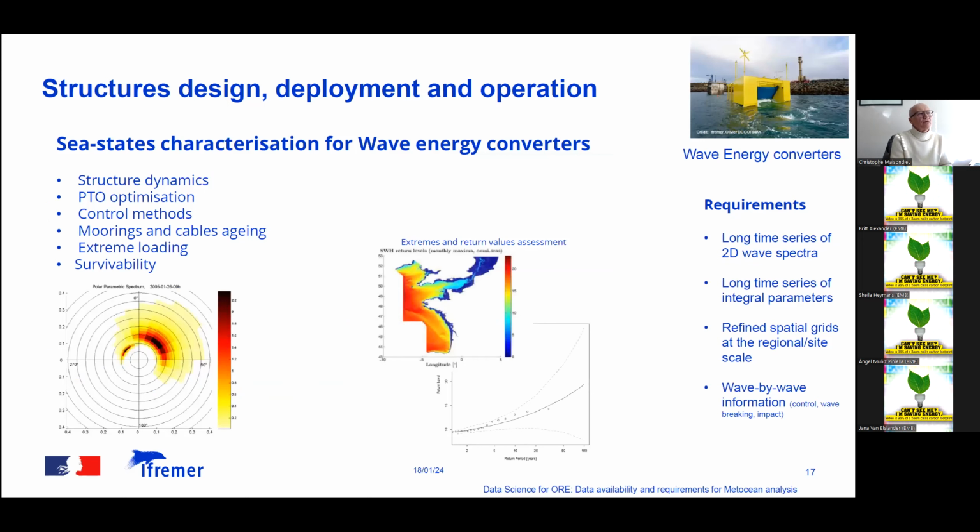When we look at wave energy converters, the main information we require is information on sea states. This is to assess the dynamics of the structure and the response of the structure. It's also for the optimization of the power takeoff. This also sometimes requires the development of control methods, which require information, I would say, almost wave by wave. These structures will be moored, and we also will have export cables. So we will have to study the influence of waves on these.